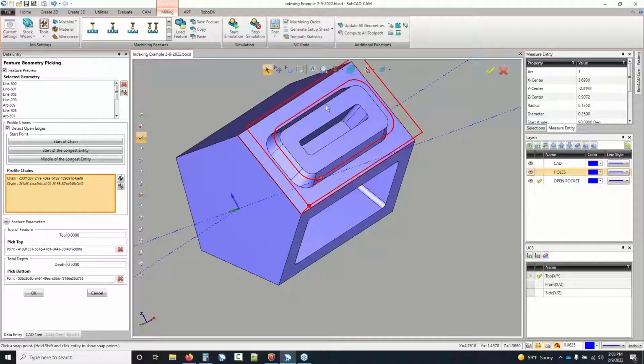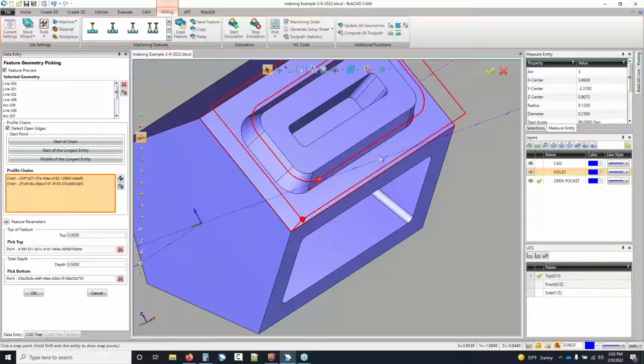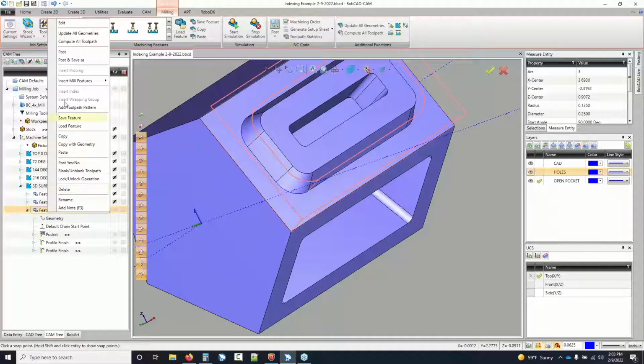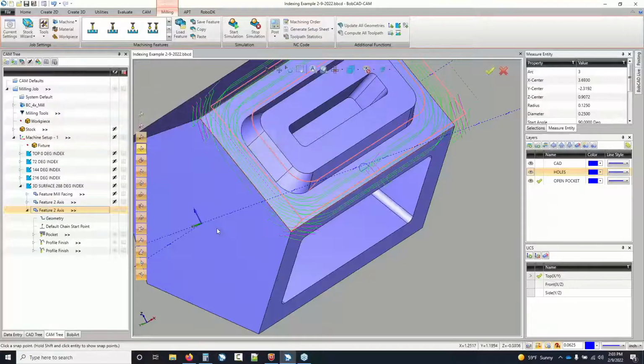The only part of this toolpath that's going to have a finish pass, which honestly, we really don't need anyway, is the solid line. So I'll go ahead and put my start point there. This outside dotted line shouldn't have any finish pass applied to it. So I'll hit OK. And then because we used the advanced pocket earlier, I can actually just compute this toolpath.